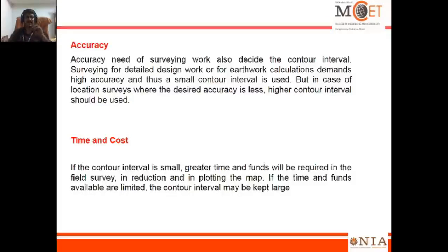And based on time and cost, if the contour interval is small, greater time and funds will be required in the field survey, in reduction and in plotting the map. If the time and funds available are limited, the contour interval may be kept large, and we can complete the work very fast.